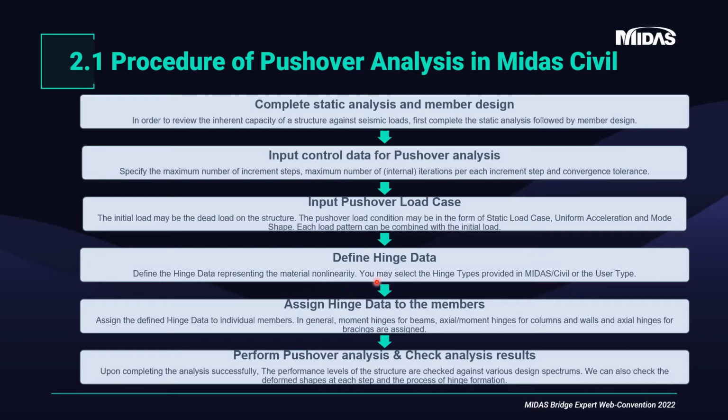Then we define the hinge data. So we can define the hinge data representing the material nonlinearity, the inelastic hinge. There are many types of hinge that are provided in Midas Civil software. Then we assign this hinge data to the members. Then we perform the pushover analysis.